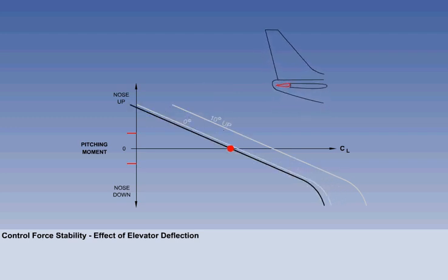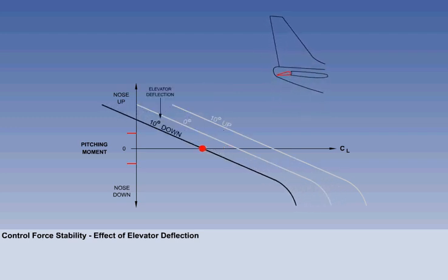Now the aircraft is continuing to maintain level flight by decreasing the angle of attack as the indicated airspeed is increased, until once again it is in equilibrium at a higher airspeed. To hold this angle of attack at a higher airspeed, the elevator must remain displaced at a position 10 degrees down from neutral. A momentary increase in angle of attack generates the same stabilizing nose-down pitching moment.